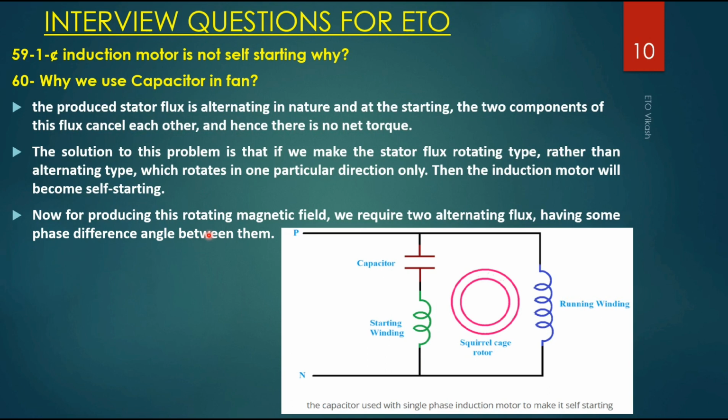phase difference angle. By this we are producing the rotating magnetic field, same as in a three-phase induction motor. So by using the capacitor we are creating the phase difference, and we are making the single phase induction motor self start.